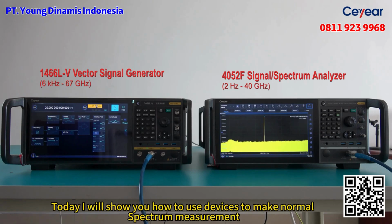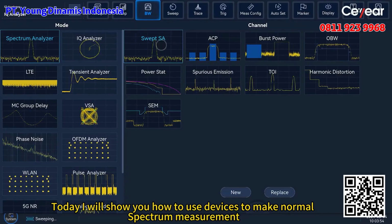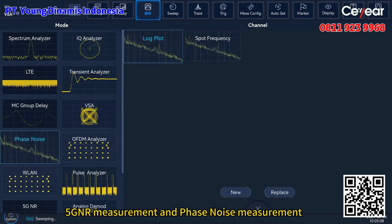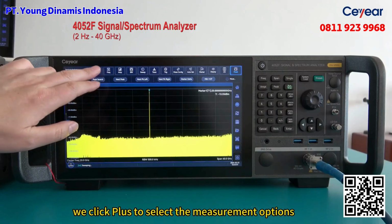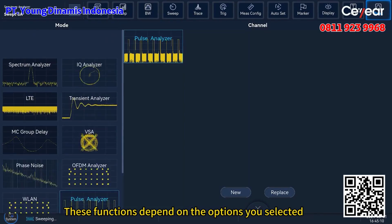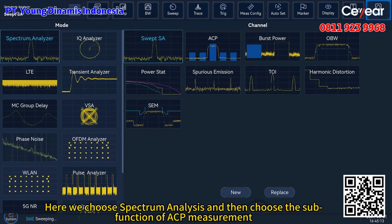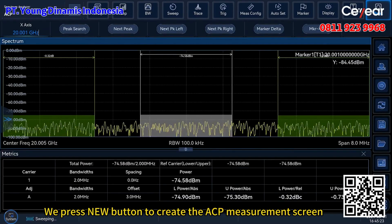Today, I will show you how to use the device to make normal spectrum measurement, pulse measurement, 5G NR measurement, and phase noise measurement. Firstly, we click plus to select the measurement options. These functions depend on the options you selected. Here we choose spectrum analysis and then choose the sub-function of ACP measurement. We press the New button to create the ACP measurement screen.